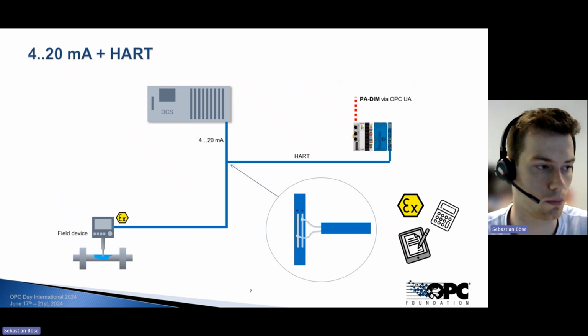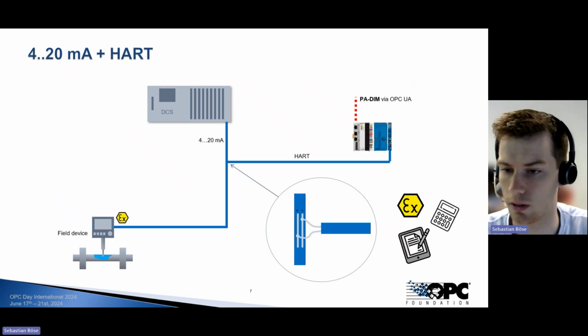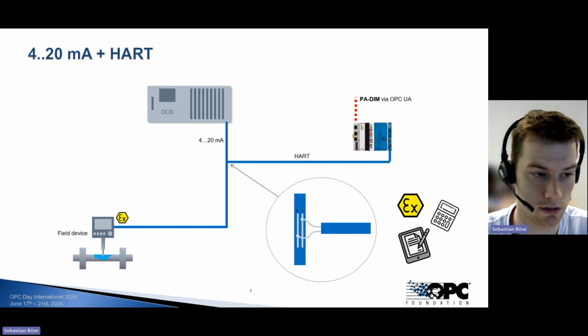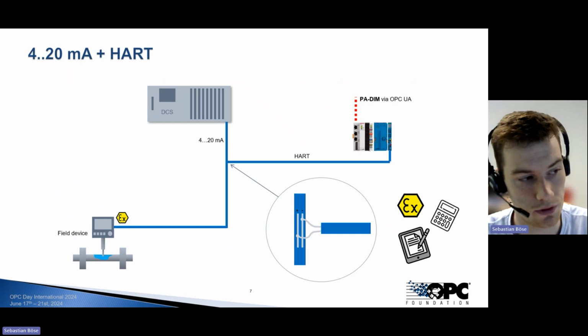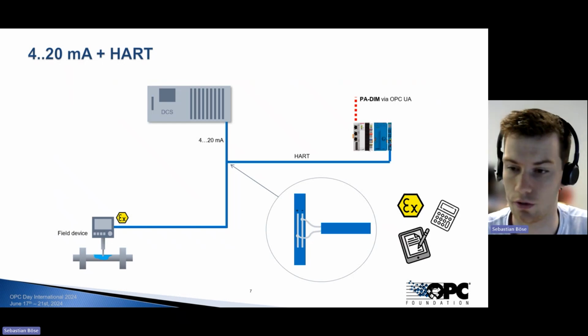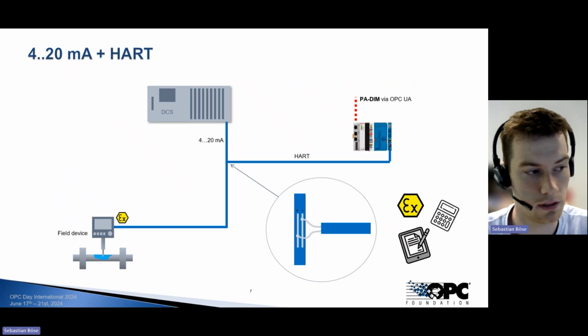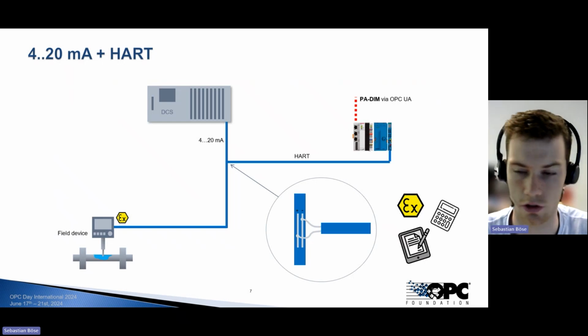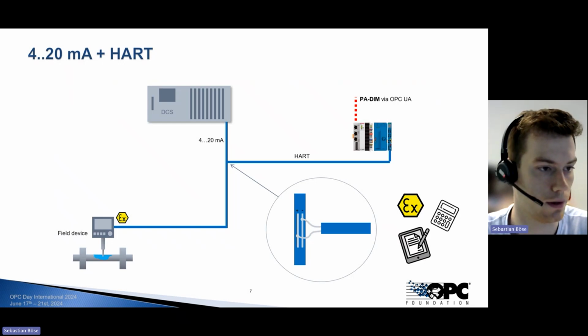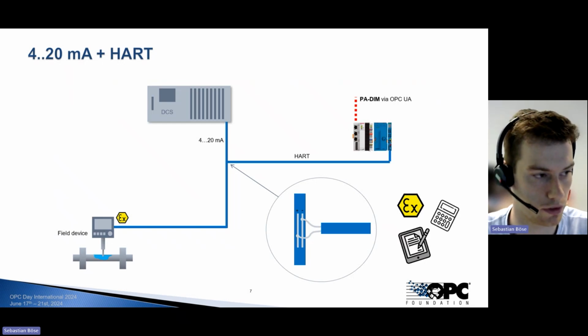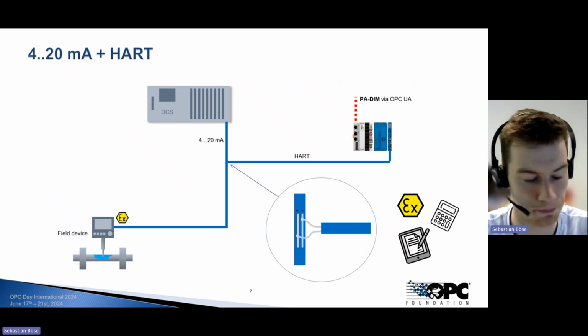It's also because NAMUR and the NAMUR architecture is something we want to add while the whole process plant is still running. So we don't want to interfere or touch the existing system. And if we do something like that, we're really touching the intrinsic safety and the proof of intrinsic safety. So technically it's possible, but it's something we really need to consider, whether we want to touch this intrinsically safe loop. But just to show you that it's also an option for us.